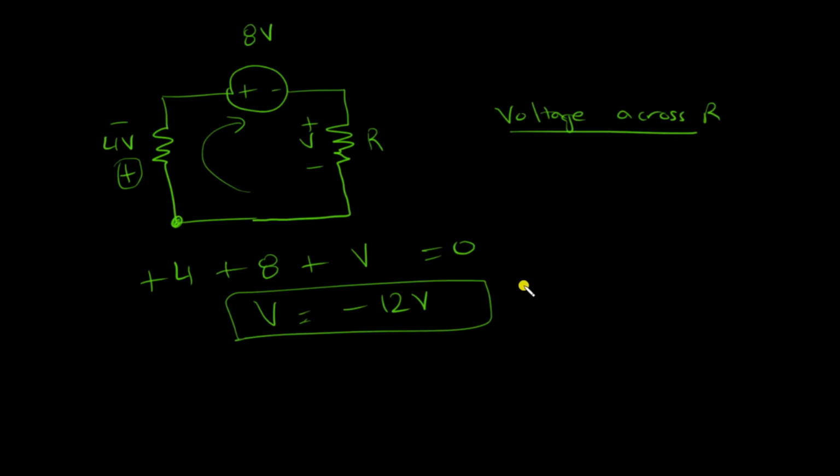So this is how you apply Kirchhoff's voltage law. Now to make things more clear, the backing behind Kirchhoff's voltage law is the law of conservation of energy. Voltage is the energy that every charge has. So if you're moving around a loop and a charge comes back to its original position, the charge has zero energy because it has spent all its energy around the loop. That would mean it would always use its entire energy across each element, so that it comes out to be zero, and this is why there's a zero here. So this is how Kirchhoff's voltage law works.